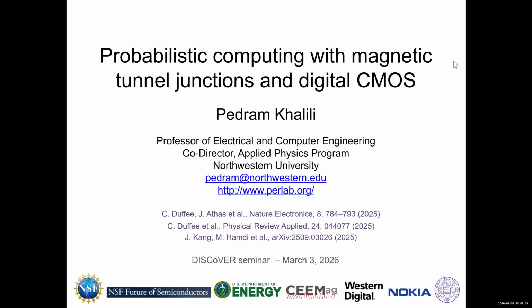So what I will present today is basically a subset of the work that is going on in my group, where our goal is to take some emerging spintronic devices, in particular magnetic tunnel junctions, of which there are a few different flavors that I will introduce along the way, and to use them in conjunction with conventional digital CMOS integrated circuits to do probabilistic computing.